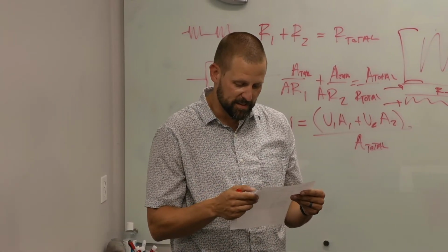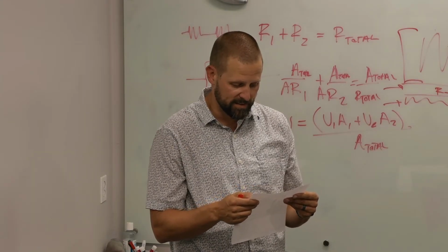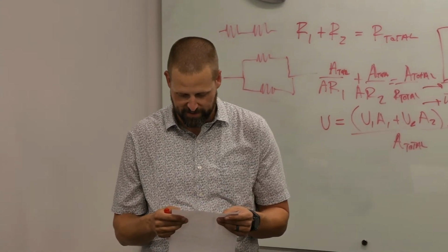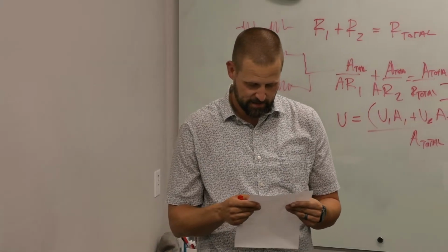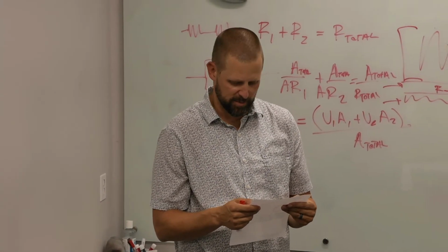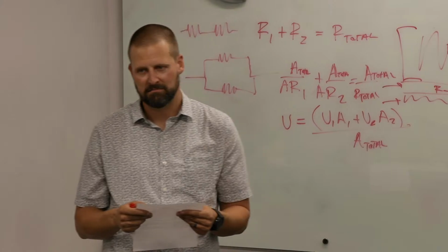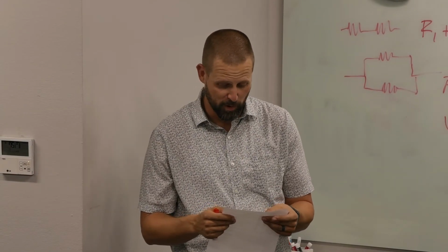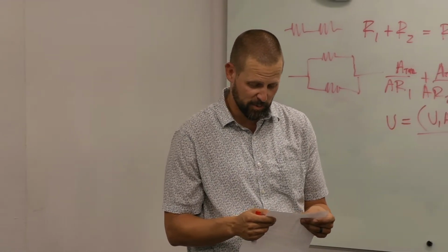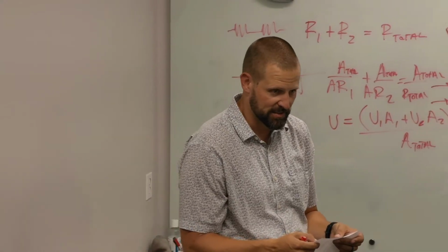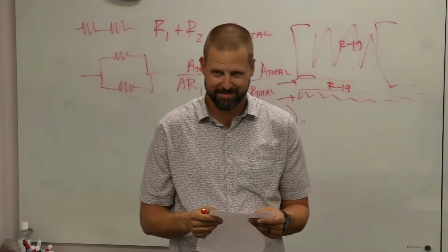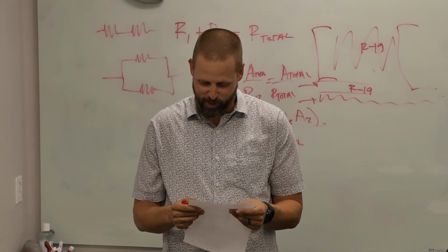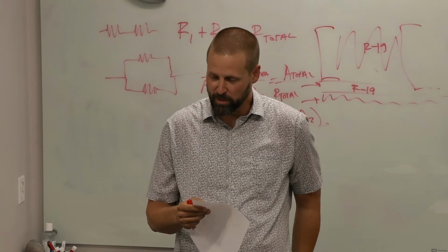Let's do something similar. So if we use R12 continuous and do no cavity insulation, what would our Battleship coordinates be? I've never used this before, but now I'm going to call it that from here on out. So that'd be row 1. And what column would we be looking at for R12 insulation? Be a letter. I, yeah. So 1I, and that U factor would be 0.071.